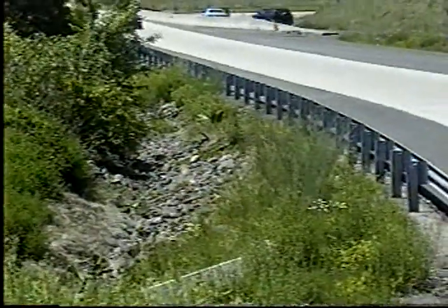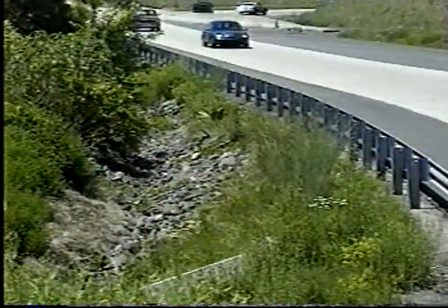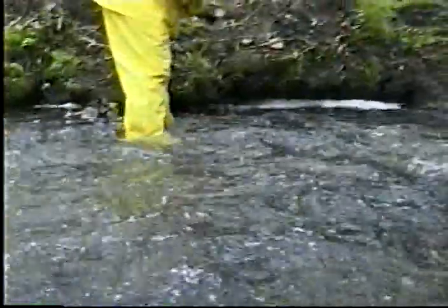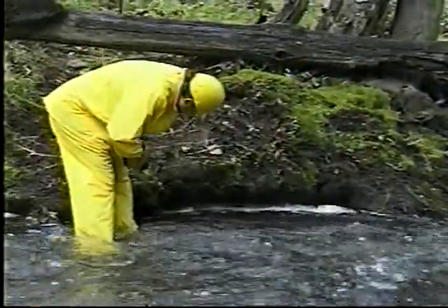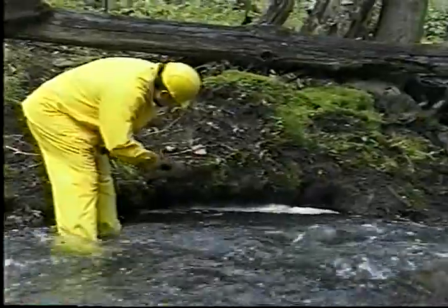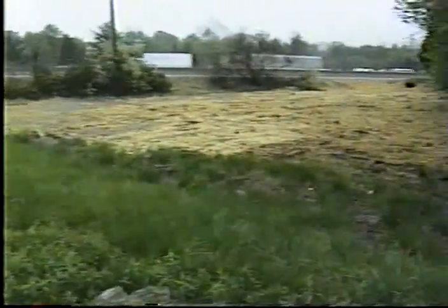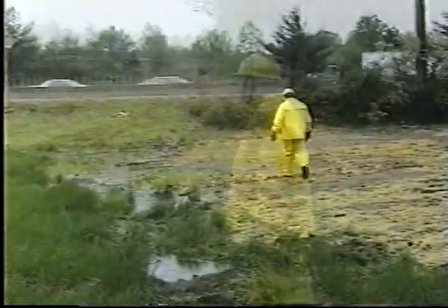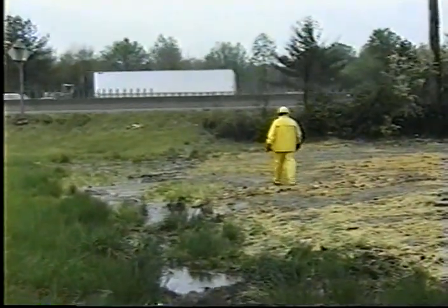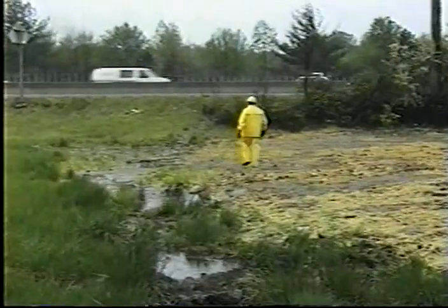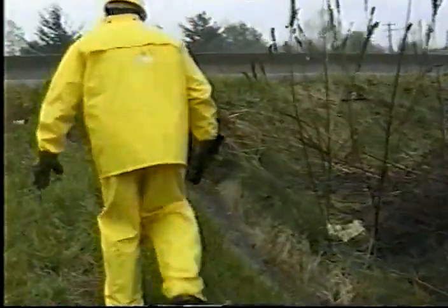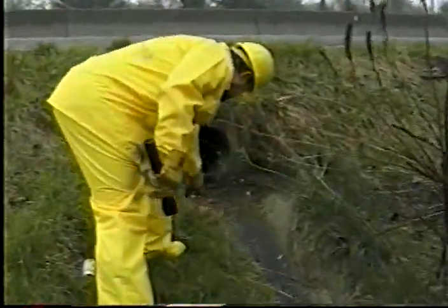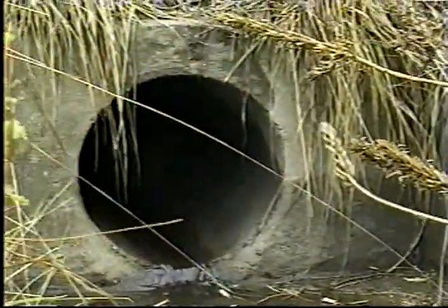Velocity of flow and direction of currents are critical factors in selecting materials. With any bank protection, take care to prevent the protection from being undercut by erosion. The leading edge of the protection should also be shielded from erosion. Other drainage appurtenances that need to be inspected and maintained include wash checks, energy dissipators, head walls and slope drains. As with all structures, inspection should be directed at critical areas that could fail.